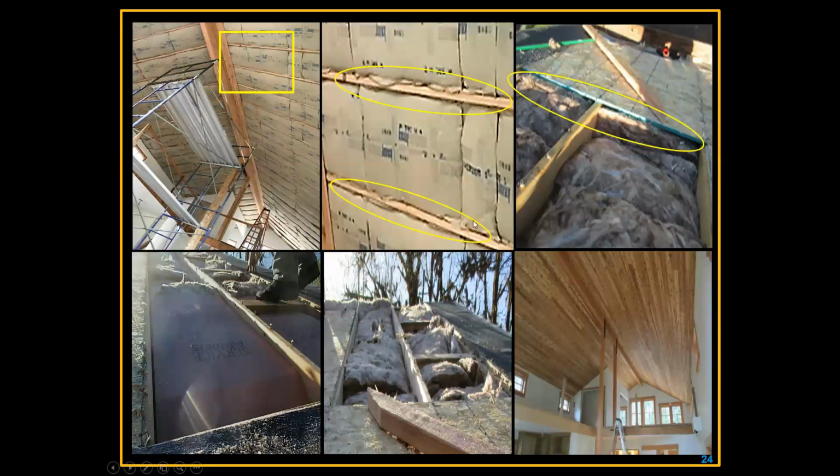Here's an example of, again, this is about air getting into an assembly. So this is a roof system. This is in Southern Oregon. And of course, they side stapled. And even though that's legal by code, it is not best practice and it creates problems. And the proof is in the pudding here.